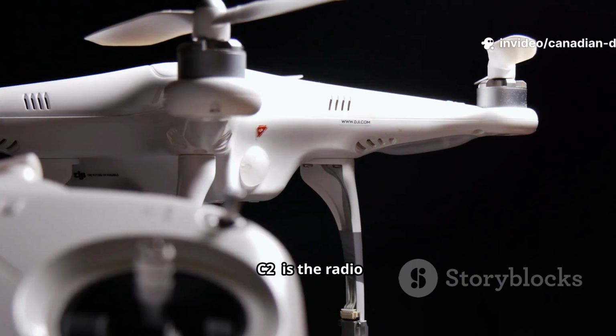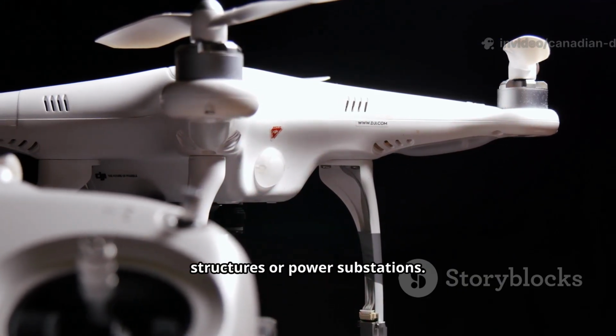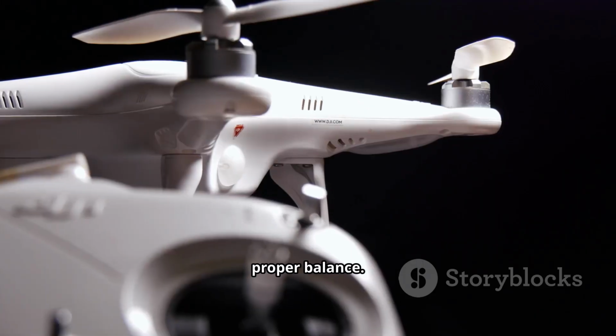The communications link, C2, is the radio between controller and drone. Watch for interference near metal structures or power substations. Payloads like cameras affect flight time and handling, ensure proper balance.